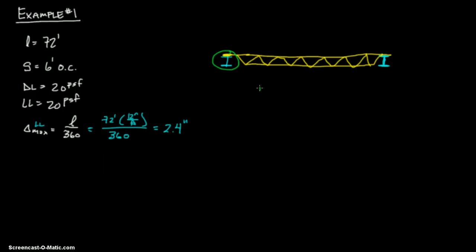You can get the I, and you can get your S, and you know that bending is M over S. So you pick a beam with your S to make sure that you get your FB, which maybe is 0.6 FY. Let's assume that equals FB. So let's say 50 KSI, and this may not be true, this 0.6 is my assumption.